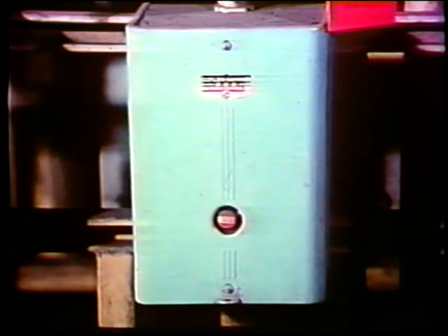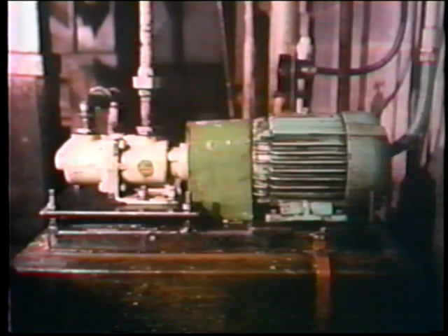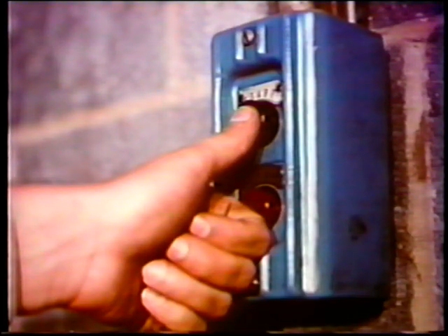The second step in the troubleshooting process is to question. The electrician needs to find out the symptoms of the controller malfunction. From the operator, the electrician discovers that the liquid level of the sump is high. Normally, when the liquid level is high, the motor should start when the start button is pushed. But in this case, it won't. This is the only symptom that the operator has been able to identify.